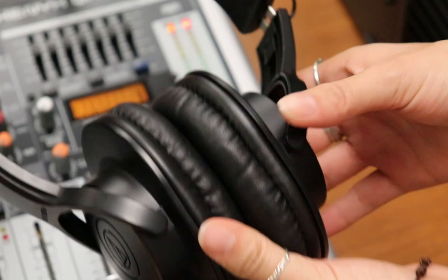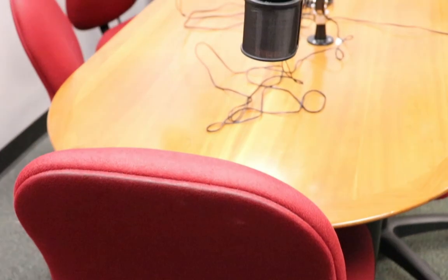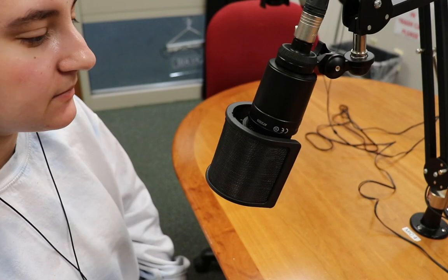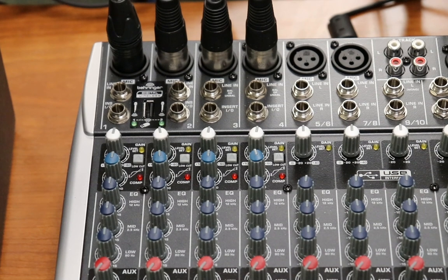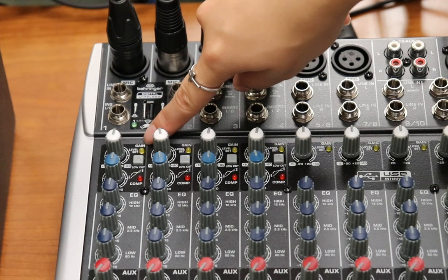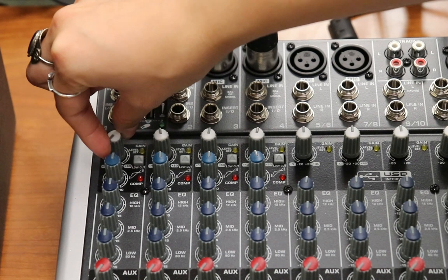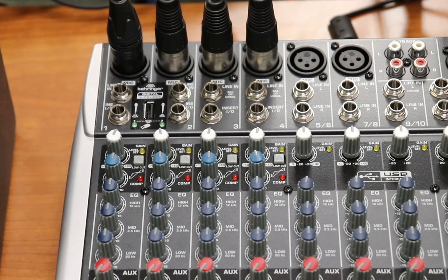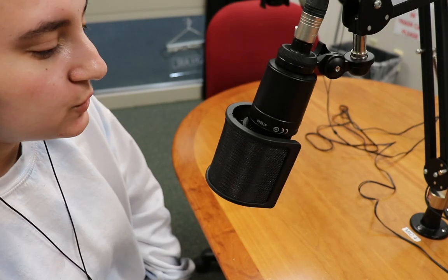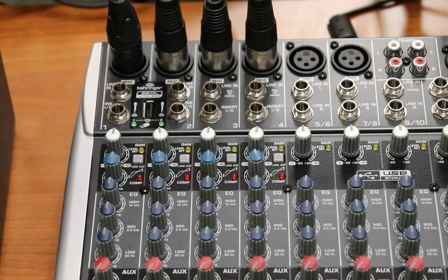Now it's time for your sound check. Have everyone around the table speak into their mics one at a time. This will be able to test the loudness of each channel. You can adjust the amount of pickup on each microphone by adjusting the gain knob for each at the top of its column on the mixer. Higher gain will pick up more sound, including room noise like air conditioners and computer fans, so adjust thoughtfully.